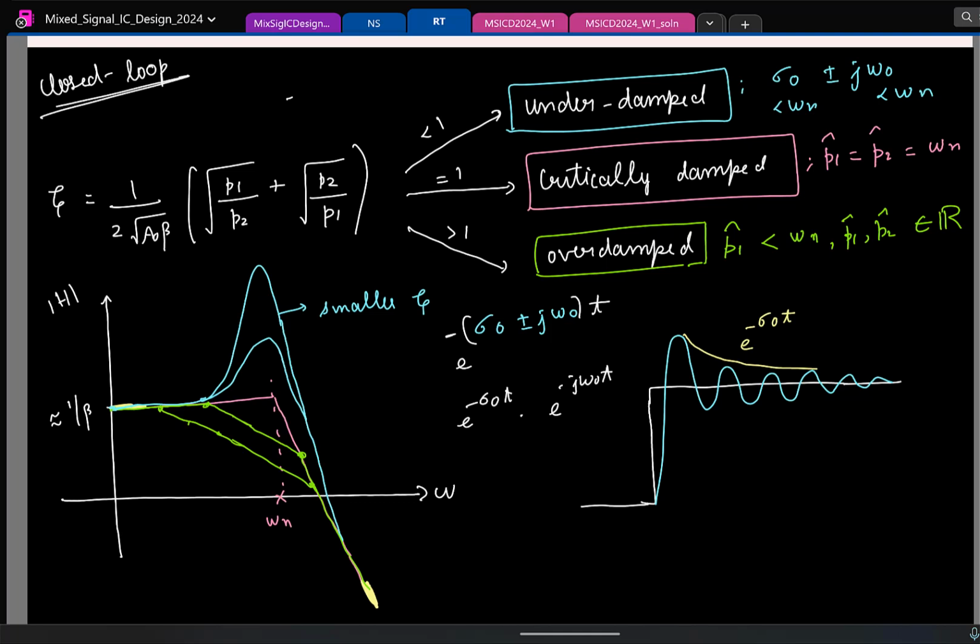Okay, great. So now if I look at the critically damped case, how will the response look like? No, it's critically damped. See, it will be an exponential. There will be no sinusoidal ringing. Think of it like this. If zeta is 0, it is going to oscillate properly. As zeta increases from 0, the oscillations start to die. And exactly when it is 1, there is nothing oscillating.